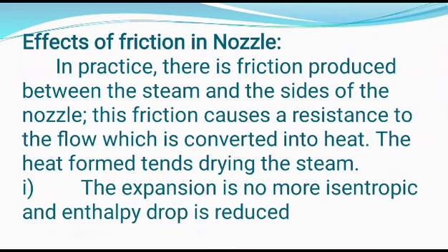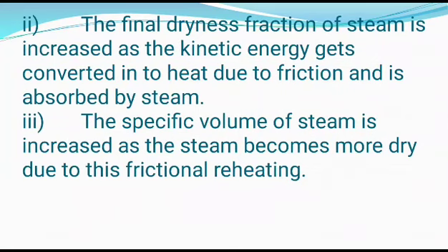First one is the expansion is no more isentropic and enthalpy drop is reduced. Second, the final dryness fraction of the steam is increased as kinetic energy gets converted into heat due to friction and is absorbed by the steam. And third one is the specific volume of steam is increased as the steam becomes more dry due to frictional reheating.